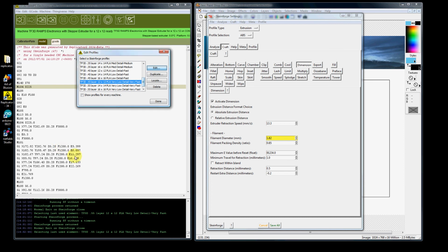So every line has a feed rate and total extrusion time, which is really handy because if you lose connection with your printer and it only sends this last G-code, it's only going to run until it runs out on this line or how much is actually in the buffer. In previous versions, the F and the E were not there.